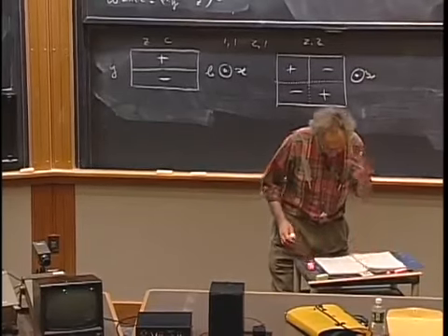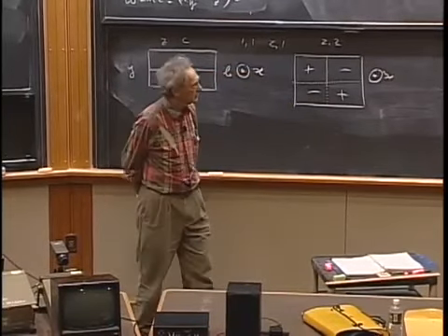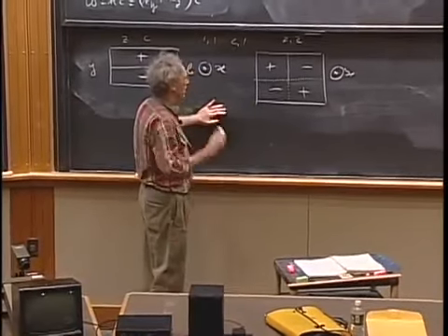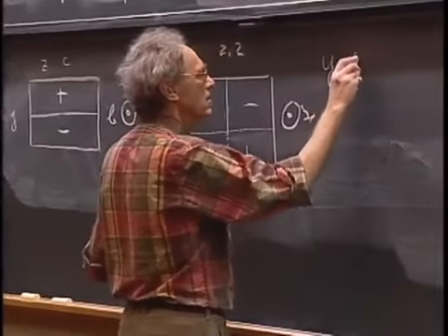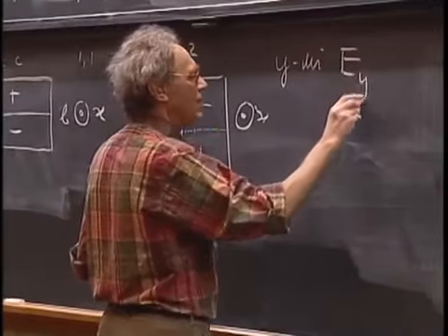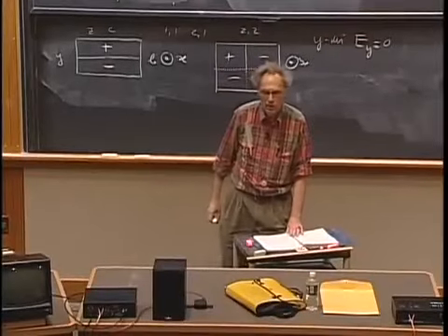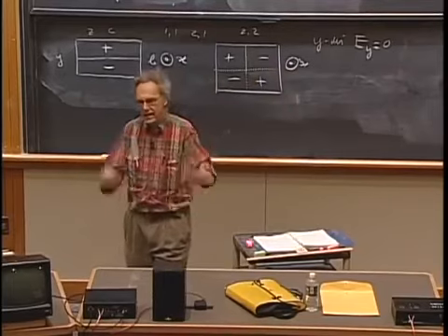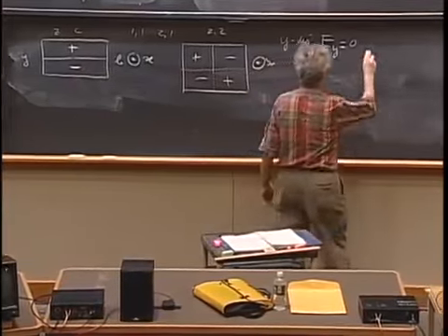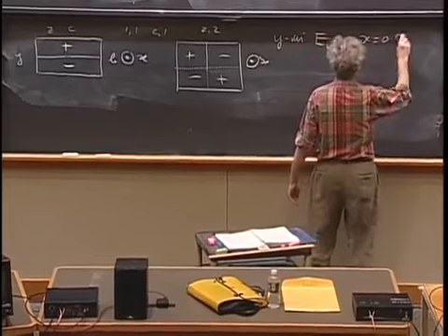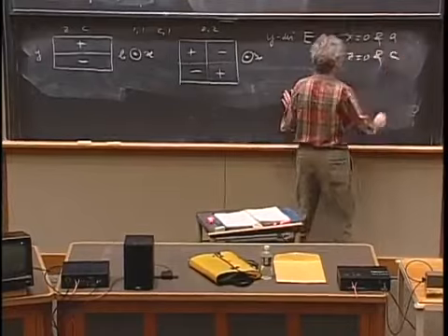Now, independently, I can look at the Y component of the E field, because I only looked at the X component. So let's now look in the Y direction, and let's ask what is the problem with EY. Well, EY also has to become 0 when, in a plane, it becomes the tangential component. And therefore, EY must be 0 when x equals 0 and when x equals a, and when z equals 0, and when z equals c.